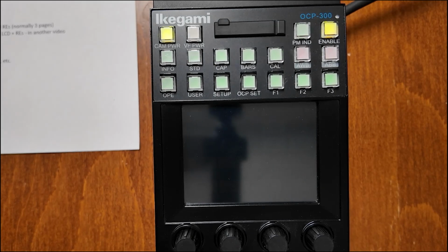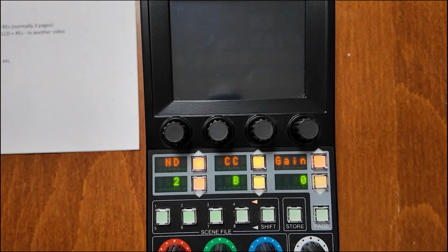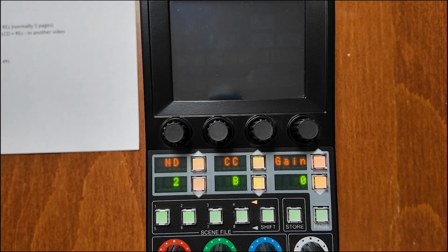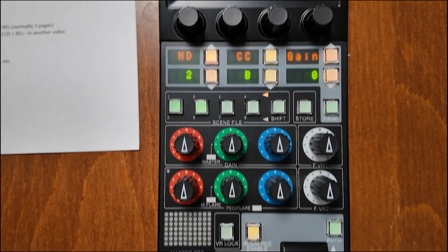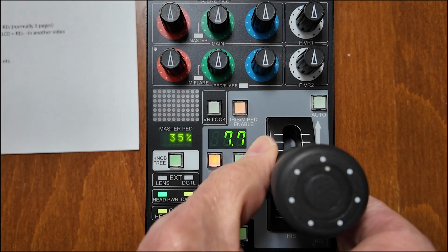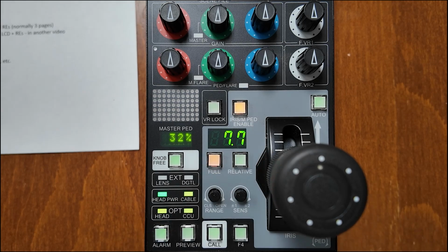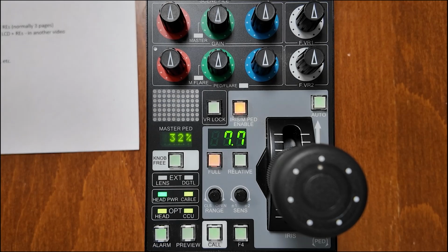Let's talk for a moment about daily setup. Normally, if a camera has been adjusted the day before, or it's generally set up okay, then the adjustment procedure is really quite simple. We would recommend centering the VRs, the painting controls that is, or potentiometers. I would also center the joystick. You can see the joystick has a pointer as when I turn it here, so I would put that at 12 o'clock as well. Iris, not particularly concerned about.